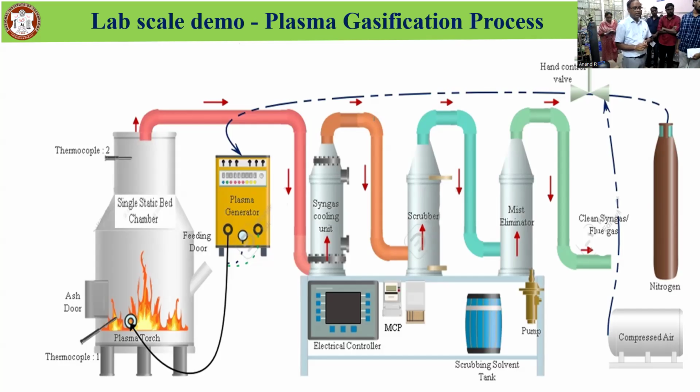Whereas if you want to control the toxic emissions after burning, we cannot go for combustion mode. We can go for either gasification mode or pyrolysis mode. In gasification mode, the raw material is operated with 20 to 30% of the stoichiometric air-fuel ratio. We can control the equivalence ratio and operate between 0.3 and 0.4. So we call it the gasification mode.